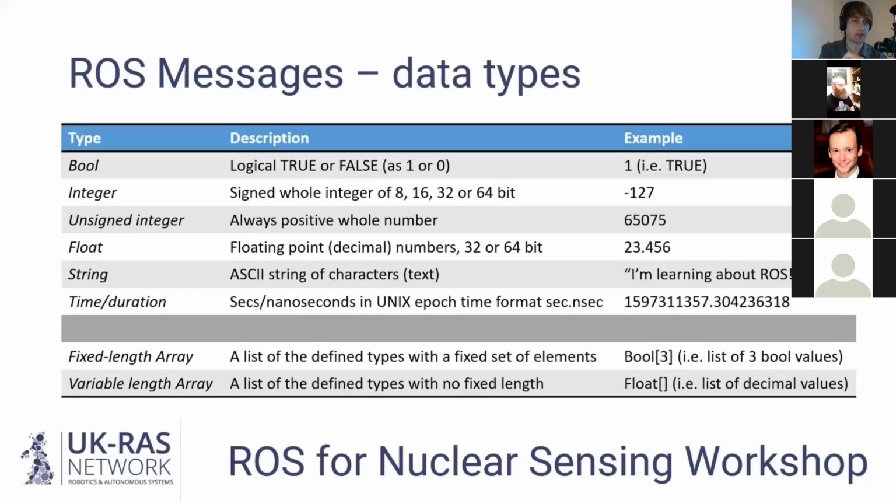That seconds dot nanoseconds is once again a format which they've decided to go with based on this Unix epoch time. Another thing I should say is that the current, or your standard, implementation of ROS is not real time. So these timings might have a little bit of skew to them anyway, because often you're running on Linux or Windows or whatever, which is not a real-time operating system. So that's just another little thing to consider. But genuinely, you are measuring the number of nanoseconds.